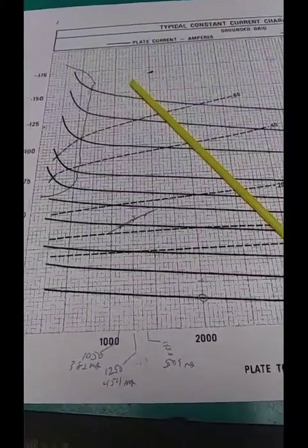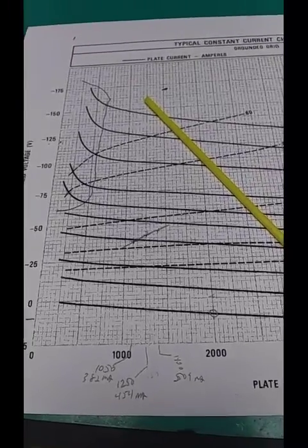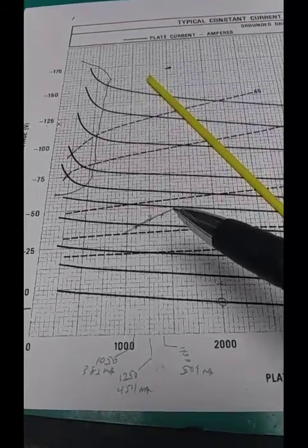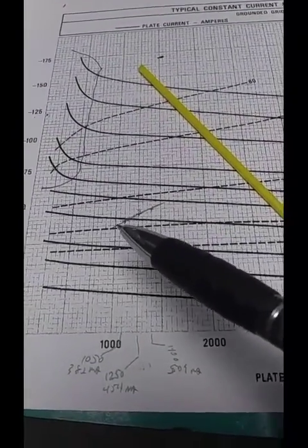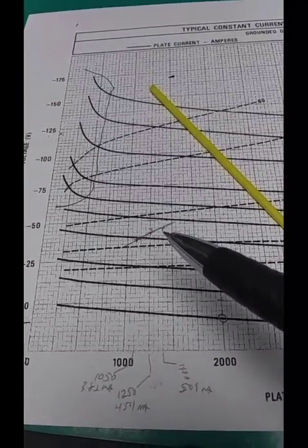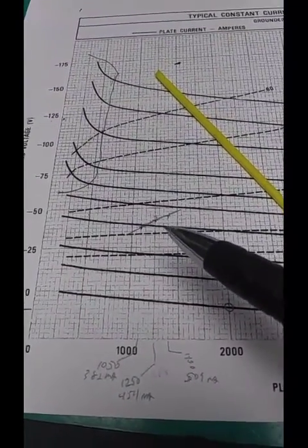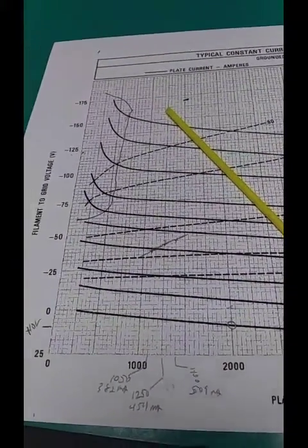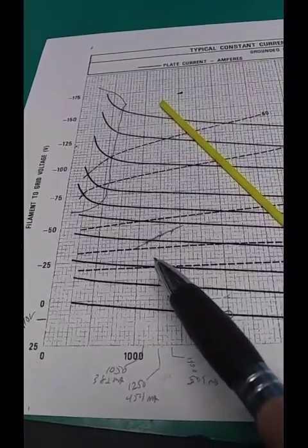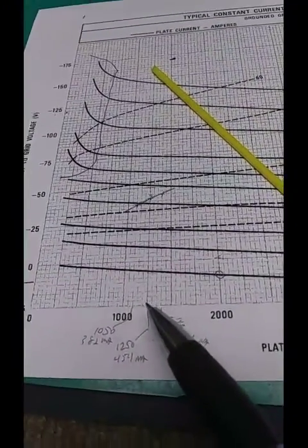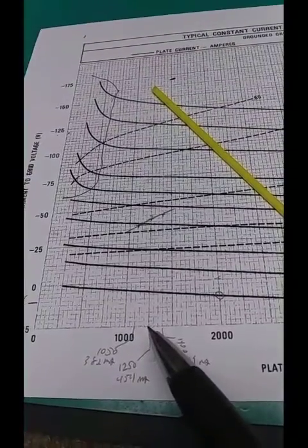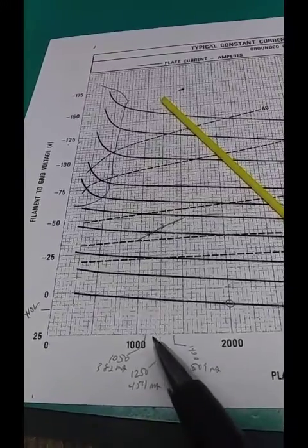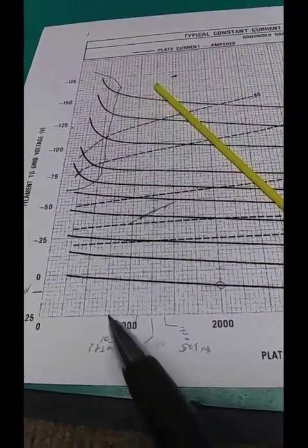Going off the proverbial reservation, what I've done is not drawn a plate line, but a plate resistance line approximately over a fairly short interval. And I'm using the assumption that the plate resistance is a median value in the middle of the operating range. And that kind of implies that the plate voltage change, let's say it's here at 1250, the plate voltage swing this way will be 750. So that suggests that the plate swing this way will be 750.